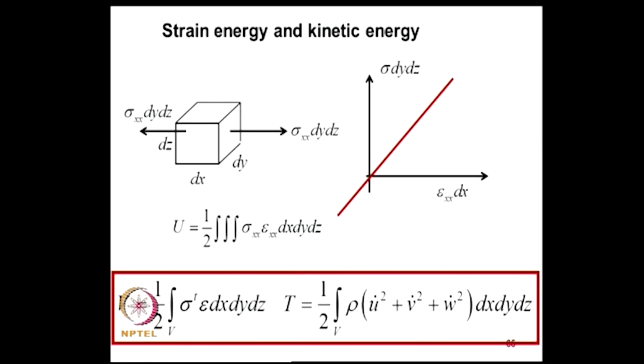We also need to discuss the energies in a 3 dimensional situation. What is the expression for energy? Now, this can be explained by considering an infinitesimal element as shown here, and suppose it is loaded. If you consider only the axial stresses, the force on this face is sigma xx into dy into dz, and this force will deform the object, and therefore this force would have done some work on that deformation, and the question is what happens to that work done. It is stored as strain energy in the system.